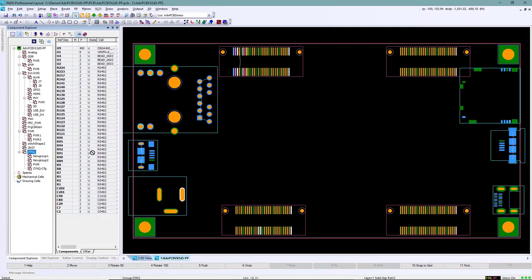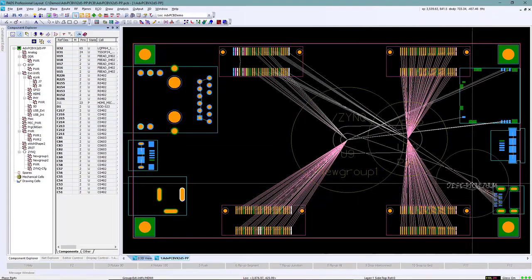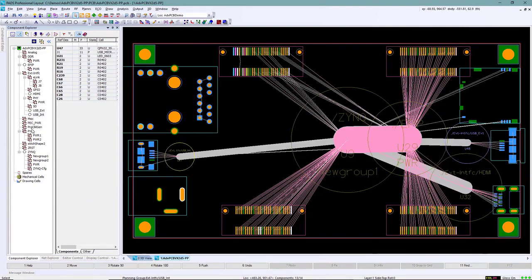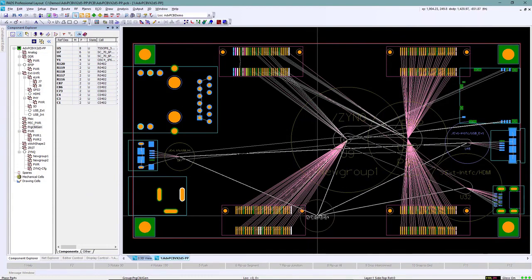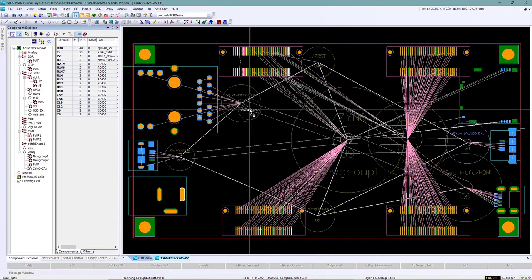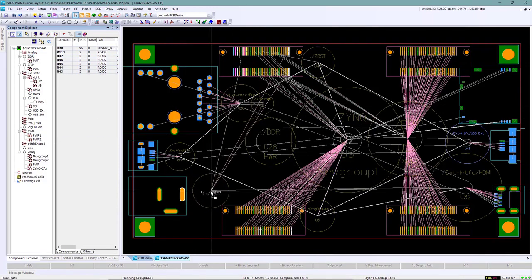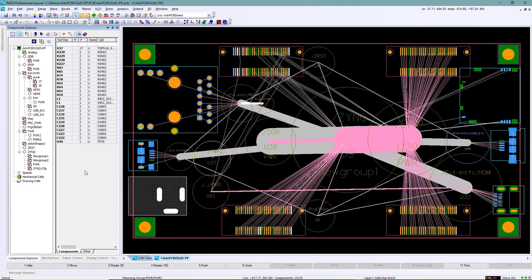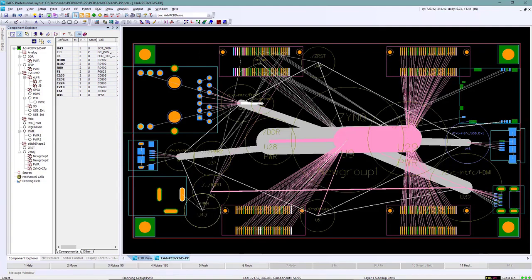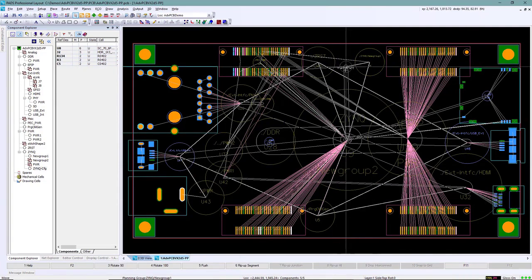Creating a rough placement with interconnect using groups allows us to plan ahead. As you can see, when placing groups, net lines vary in thickness based on the connection count. The circle size is defined by the component count and size of that group. More importantly, we can see net topology, which helps determine routing paths and where there may be congestion before we place a single part. Using hierarchical groups allows us to break up the large circuits when some of the parts will be placed on the bottom.